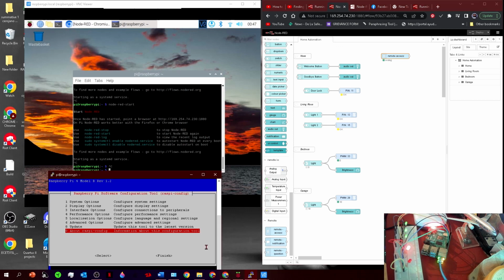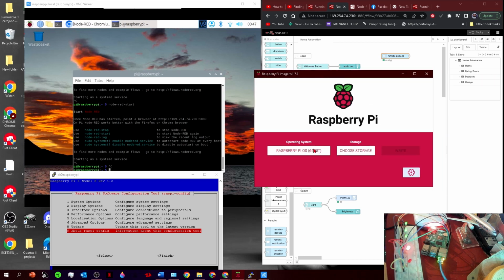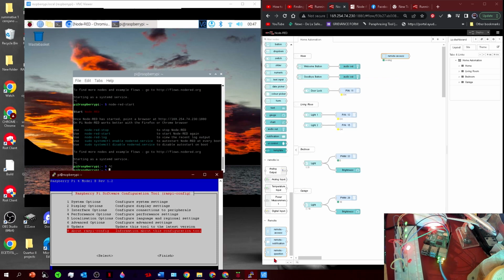this activity. So first I downloaded the OS of this Raspberry Pi to my desktop and used this Raspberry Pi Imager to transfer the OS to the micro SD card of the Raspberry Pi. As you can see now, I used the PuTTY method instead of using HDMI to a monitor. I use instead a PuTTY version for this activity.